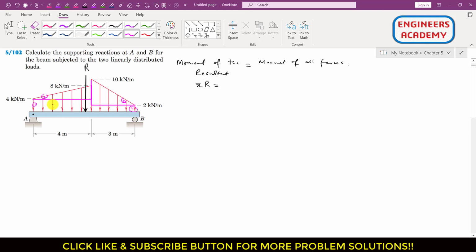So we can replace the distributed load of area 1 by resultant R1. Let's say the resultant of area 1 is located somewhere here, and the resultant of area 2 is located somewhere here. Let me call this one R1, this one R2, and the resultant of area 3 is located somewhere here. So this is R3, and the resultant of area 4, this rectangular area, is somewhere here. So this is R4.